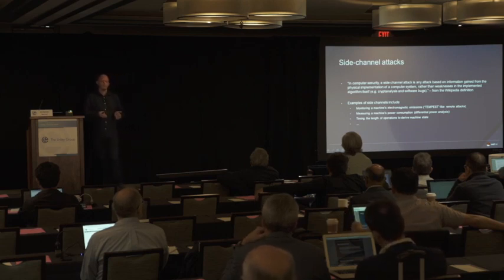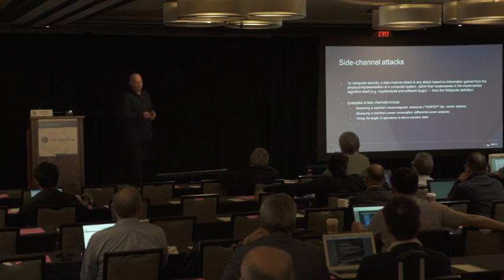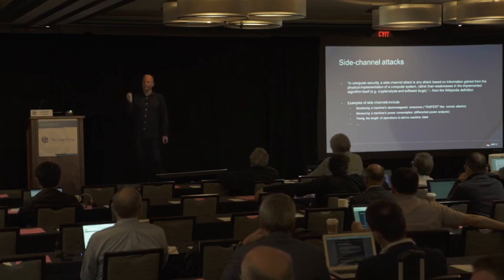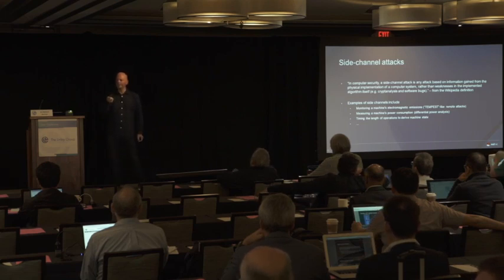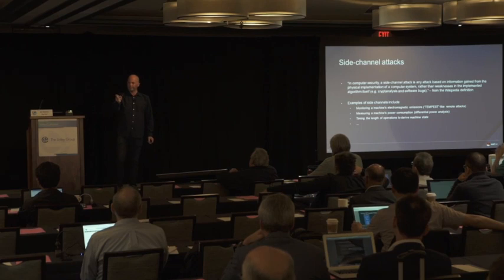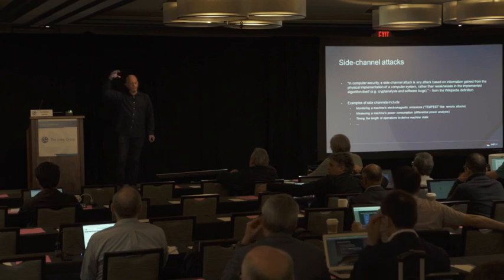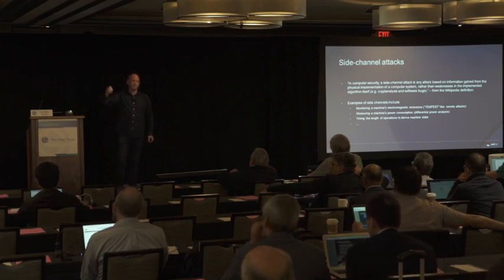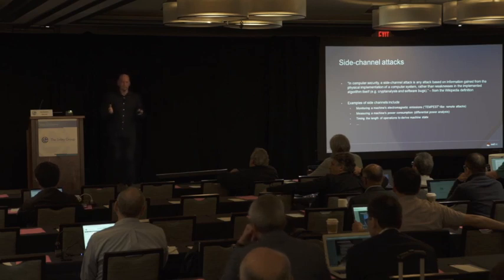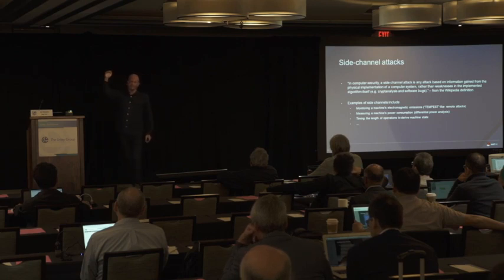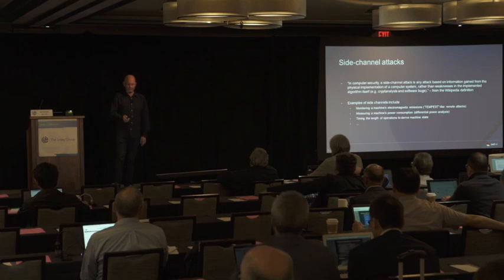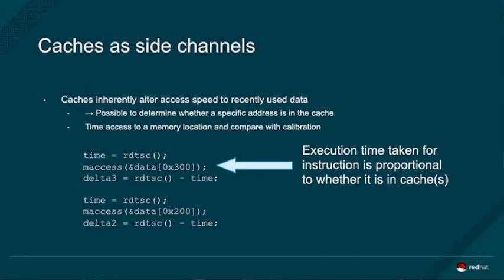A classic one is if you have a bank card with a chip on it, one thing that people like to do is differential power analysis on that chip. You put it into a reader, and then you monitor the power pins. And you see, OK, while it's doing this operation, here's the current fluctuation. You can monitor that, and you can infer something about the operation of that chip. And so the banking industry has invested large amounts of money in building tamper-resistant designs and in removing the ability for you to do this differential power analysis. But the point is there are lots of different side channel attacks, and they will continue to exist and continue to be found.